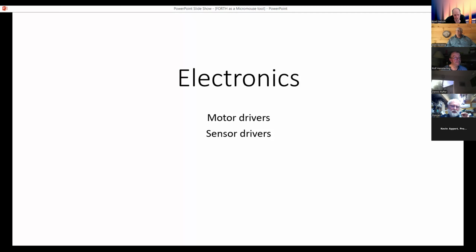If you can make the readings fast enough, you can increase the LED power dramatically. You obviously want as much LED power as possible to swamp sunlight and also to give you the maximum possible range. And I hit my bright LEDs with 1 amp pulses. I deal with some sensor electronics and optics. I've done a paper about it, and I'll put a link to that on the chat when I finish.